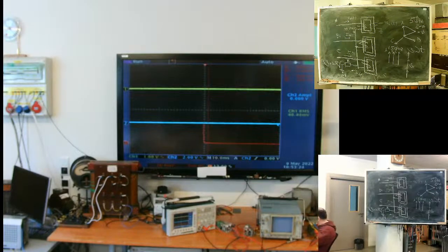Another influencing or mitigating factor is the loaded transformer. We saw load current reduces induction in the transformer core. In daytime transformers are loaded, so induction does not reach this end zone of saturation.